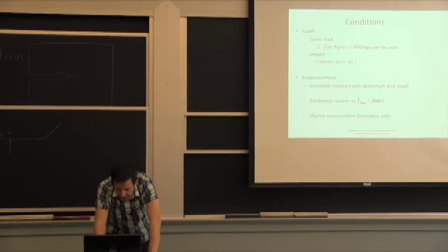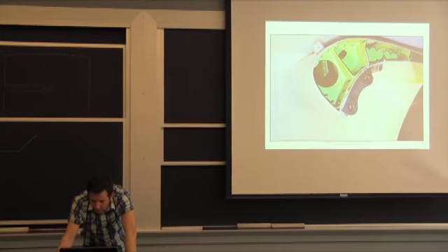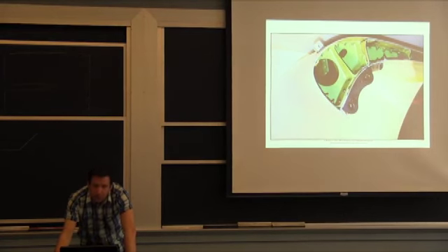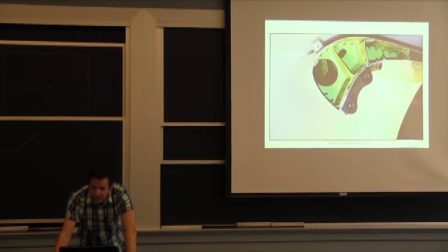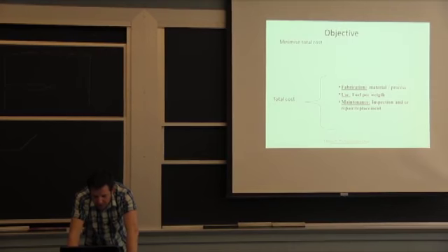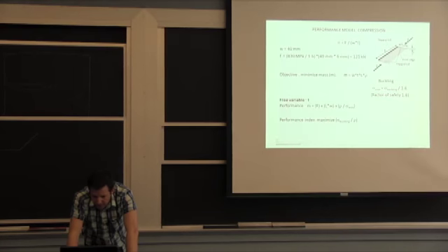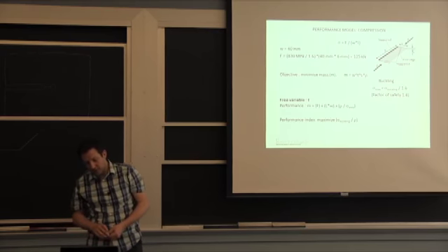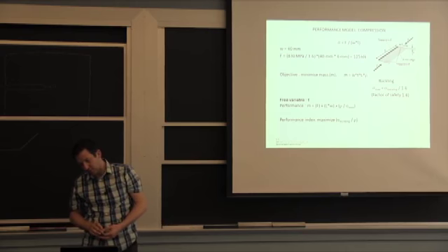So we could cast this component with all the ribs, the holes, and only need to machine this exterior surface. There's a very precise tolerance that had to be met on the exterior profile, and we couldn't get it even out of the best investment casting process. So let's try to do the optimization, because we mentioned it's a cost as opposed to weight criteria. The way we were looking at it, and this is not the exact work product, I had to redo it after I worked there, so you don't have to worry about confidentiality and stuff.